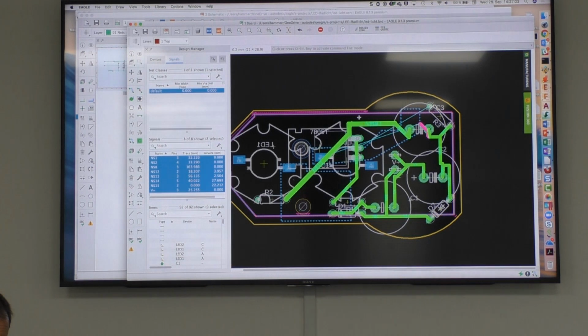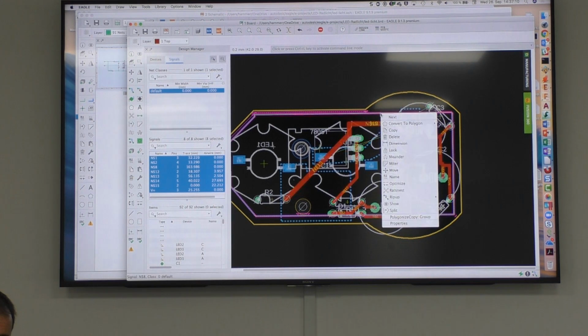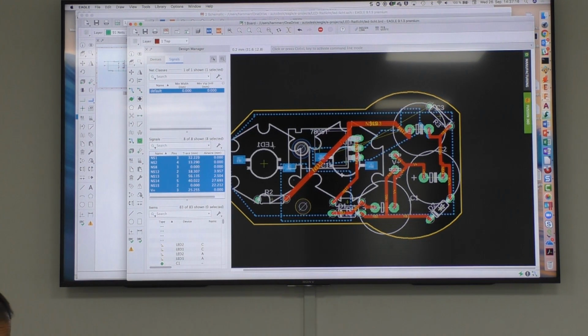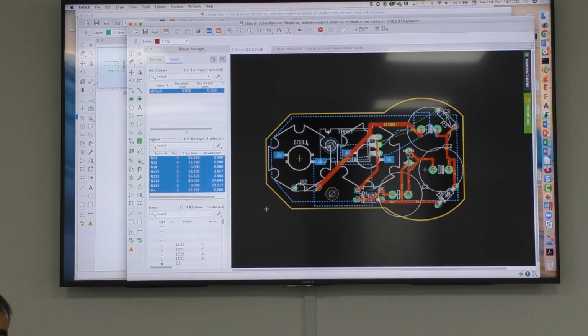The second copy. Now I have simply the wires around, and if I have wires, I can also make a polygon out of this, convert to polygon. That's in the case. Now back in the polygon. So if you import something as a drawing DXF, typically, and then I would like to make a polygon out of it, that's not possible because the DXF only has the contour, so I can't make a polygon out of it.